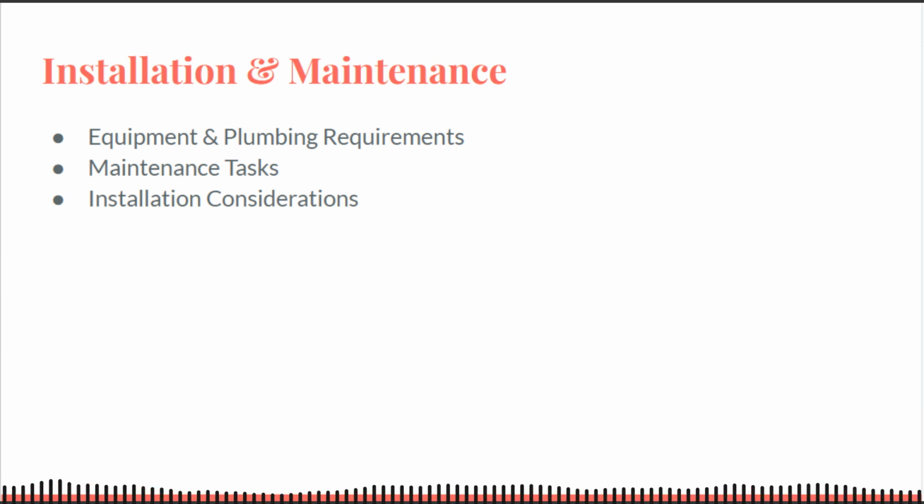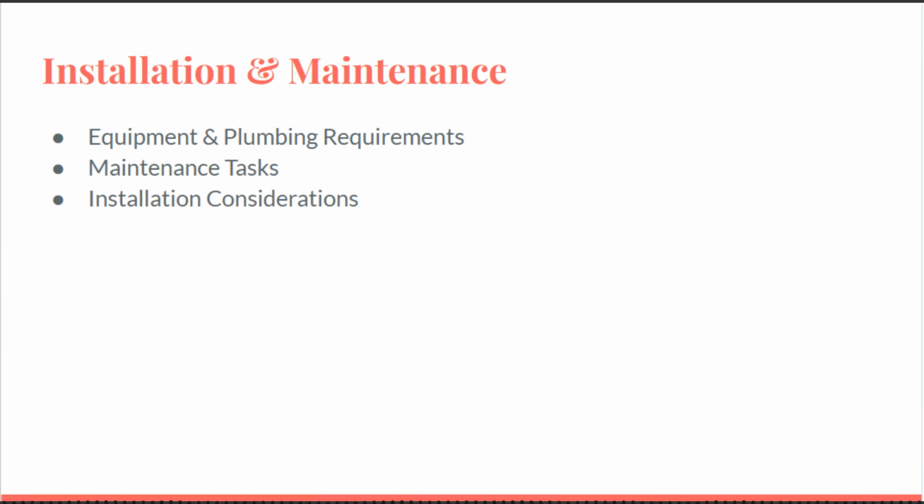AOP systems combine UV and ozone, so they typically have two connection points, inlet and outlet, for water to pass through the unit. Depending on design, an AOP unit might be plumbed in line, full flow, or in a bypass loop, side stream. For example, CMP's AOP 50 is a full flow unit with 2-inch unions, certified for approximately 50 gallons per minute flow. Whereas the smaller AOPS 25 uses a 3/4 inch side stream loop at approximately 20 gallons per minute. Adequate flow rate is important.